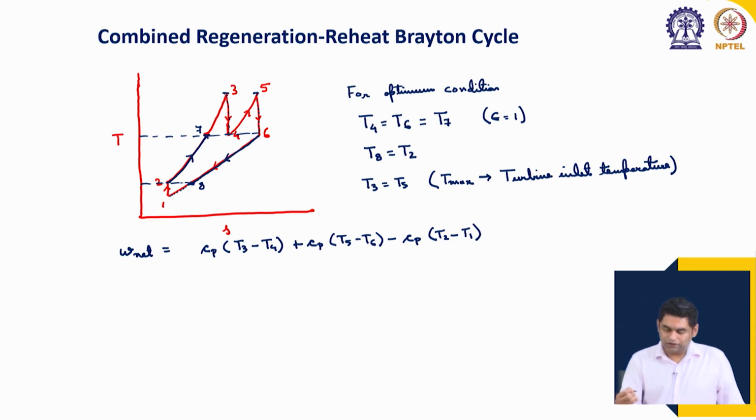So, this is the net work output, and this is similar to the case with only reheat, because here regeneration does not change the work output from the turbine, neither does it change the work input to the compressor. So, the net work output remains the same as the reheat cycle.